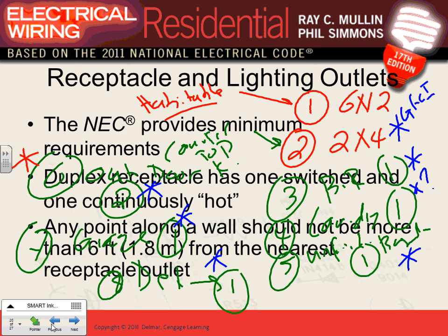Where don't you need a GFCI? 6 by 12. Bedrooms, hallways, living rooms, dining rooms. Help me here. Any other similar rooms? Playroom, gun room. If you're like my brother-in-law, and you have a room for guns. Not kidding. Protecting against water, let's say. Well, why would you need GFCI in an unfinished basement then? Dampness. GFCI guys are required in 2 locations. If you're in doubt, any damp location or any wet location, you're talking about GFCI.